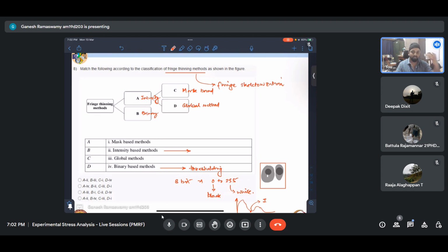Some years later, in parallel, there was extensive research on an alternative way to find this, and phase shifting methods came about, where you just need to take 4 to 10 images of the same domain without moving it, only changing the configuration of the quarter wave plates and polarizers in a specific order. Then you process those images with some mathematical processing, and you will be able to discern with confidence the isoclinic and isochromatic parameter at that point. So those are called phase shifting techniques.